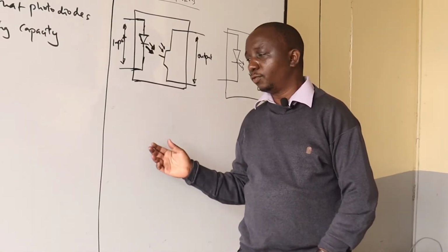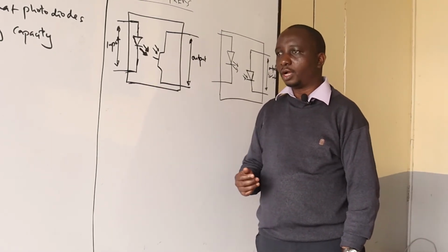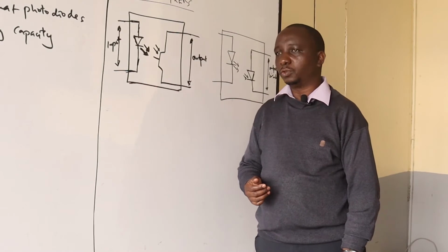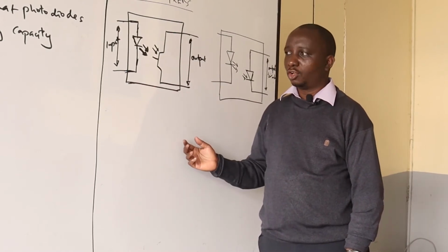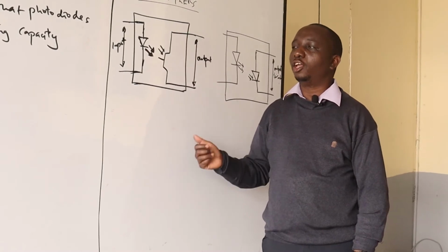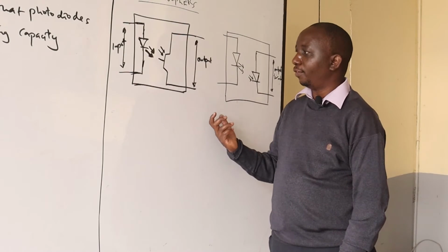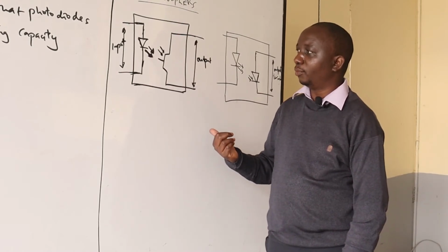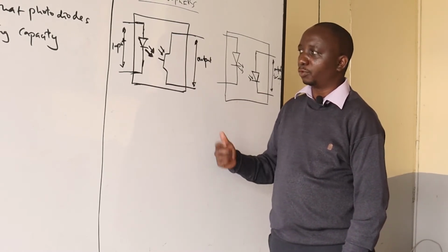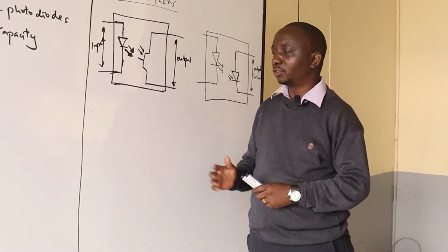Particularly when you observe our TVs, this is what happens when we turn on and we see the TV going to standby as an example. By the time you press your remote, you are activating the LED so that we're able to switch on the optocoupler to emit light to complete the circuit. So particularly, this is just an isolation circuit.